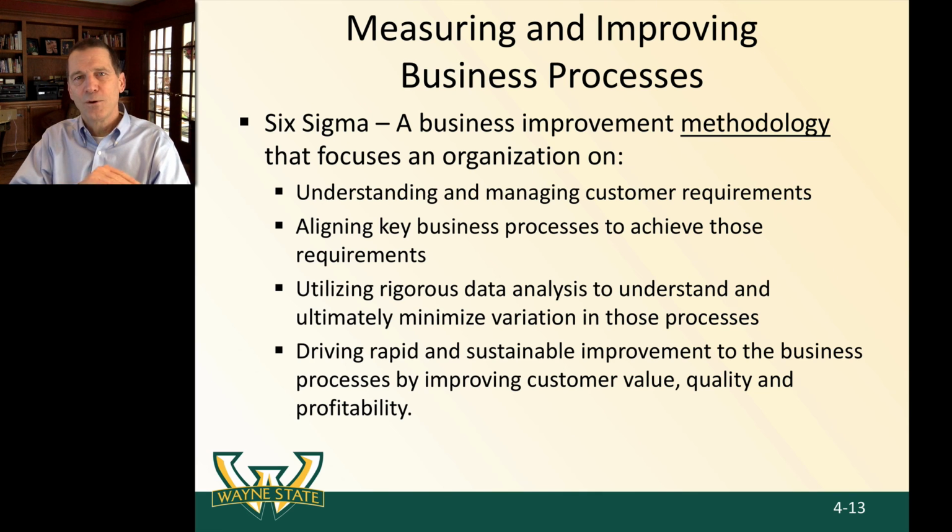And then how can we organize that process to basically center the mean? We always have process outputs that can drift to the right or the left of where we designed them and where we want them. So let's say we want 100 pieces per hour as one of the outputs of this process. Well, we could be getting 110 or 90 sometimes. So we want to center the mean.